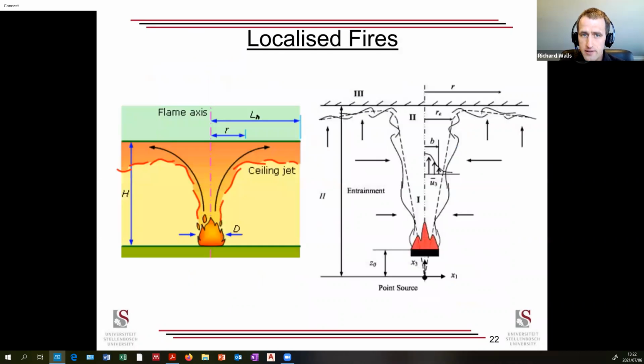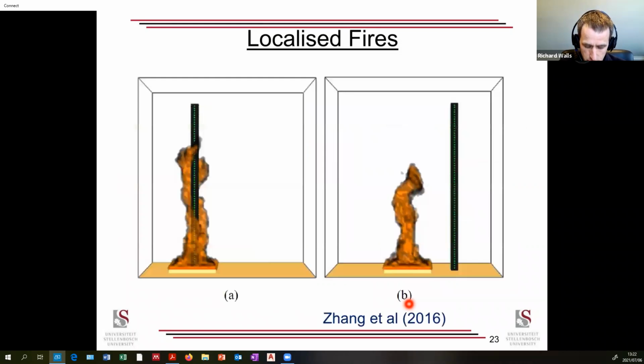But you can also get other fires. Now, in the Cape Town International airport, you would have a localized fire. You wouldn't get to flashover. You wouldn't get to full room involvement. So you'd rather have a distinct fuel package burning near a column or a beam or something. And so you can design for that. And so then you can actually generate a fire and then work out how much energy is going into your column and then calculate the temperature of the column.